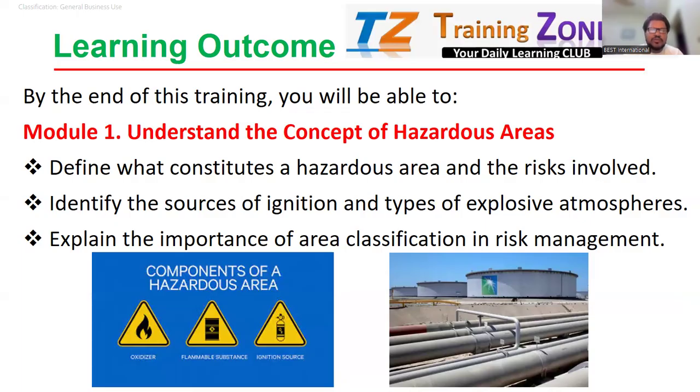So if you are the permit receiver, don't sign it until you verify that all the hazards are authentically identified, all the risks are evaluated, and the control measures are well implemented. And of course, once the permit is issued, make sure the toolbox meeting is held, the area is well barricaded, you make sure the PPE is there, and you know how to enter.